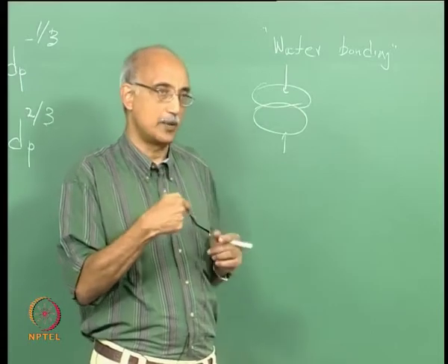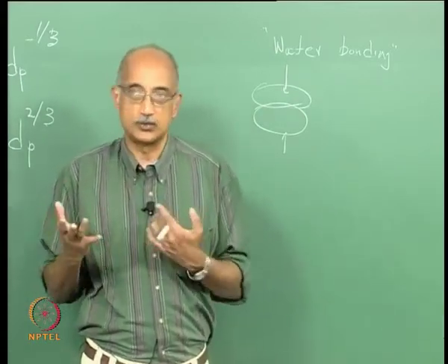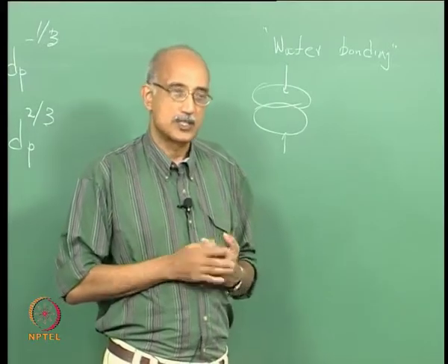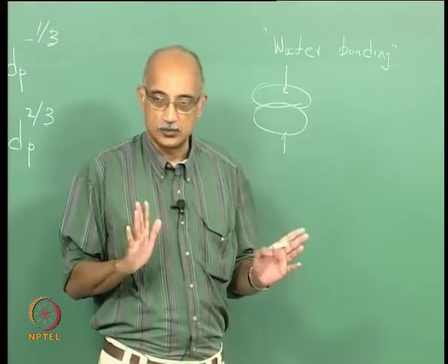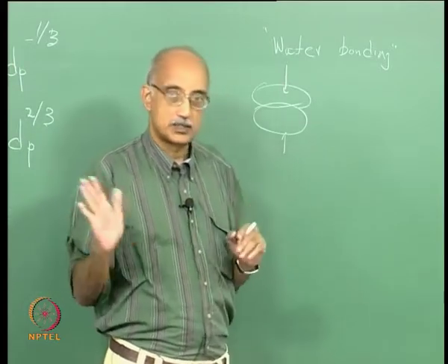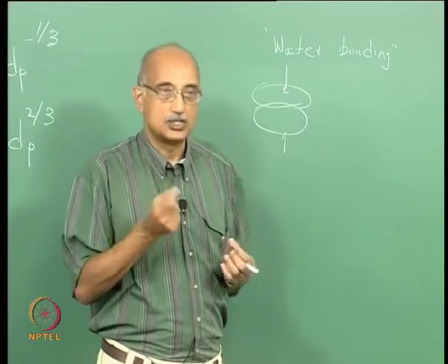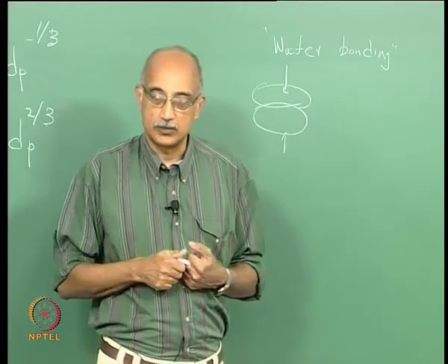And this wedge can be applied to a non-critical area of the wafer so that you do not damage the circuitry and the electronics and so on. So, that is basically how this process is done. You polish the wafers, stick them together in pairs, take them through the process until the time you need them to be separate, and then you use this tiny wedge to separate them and then process them individually.